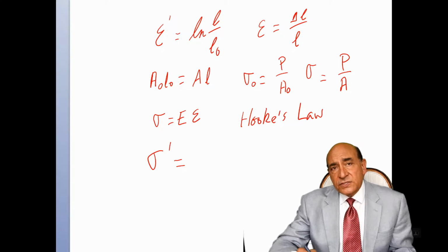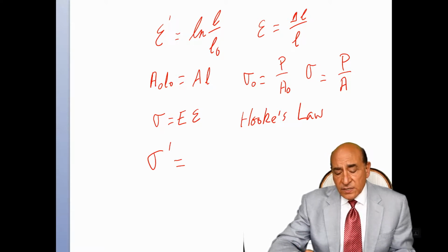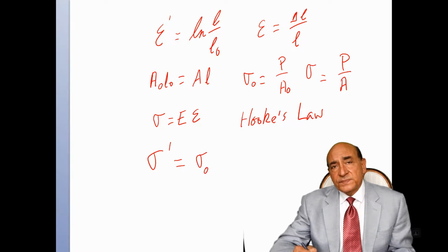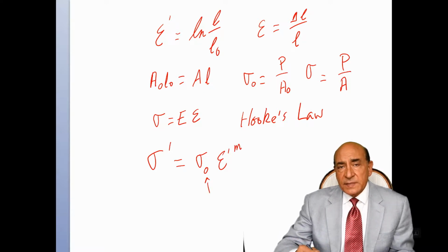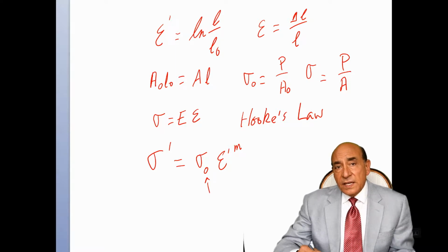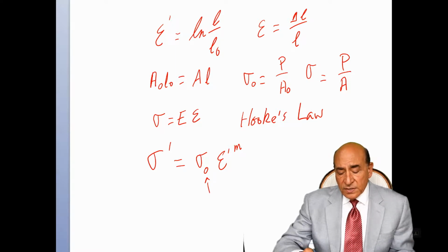So let's say that true stress is equal to a parameter sigma 0 times the true strain to a power m. And this parameter is called strength coefficient.